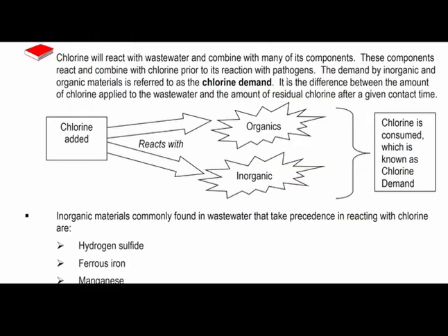Chlorine demand. Chlorine will react with wastewater and combine with many of its components. These components react and combine with chlorine prior to its reaction with pathogens. The demand by inorganic and organic materials is referred to as chlorine demand. It is the difference between the amount of chlorine applied to wastewater and the amount of residual chlorine after a